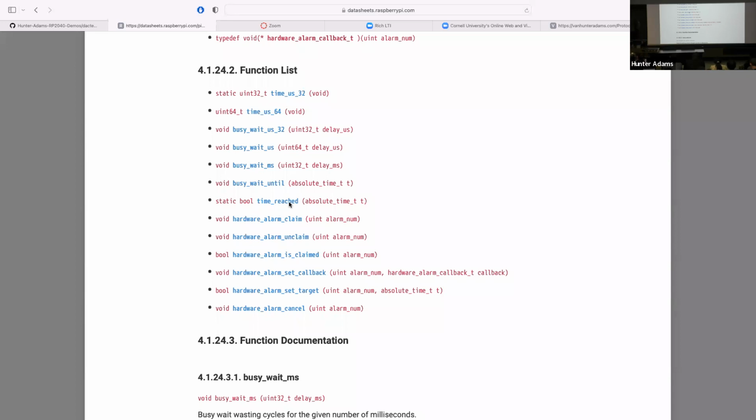You could, if you wanted to, in the interrupt service routine associated with that alarm register, rewrite the value in the alarm register to be equal to the current time as you measure from the onboard timer plus the same amount of delay, and then it would interrupt again when there was another match, right? So you could set up the logic that allows for a repeating timer interrupt. The way you would do it is set up an alarm to go off sometime into the future. When it goes off, rewrite the register to go off again the same amount of time in the future, and then it would keep going off.